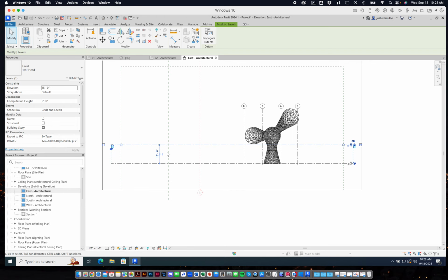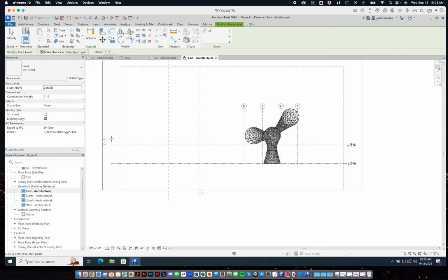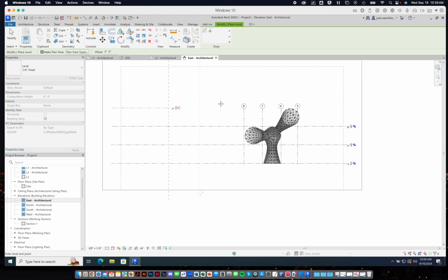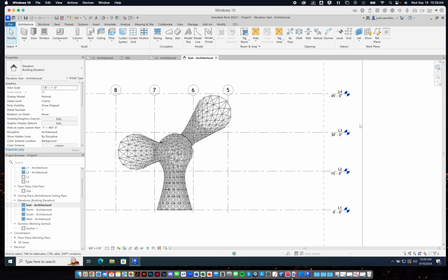All right. And let's see, I want to make another level, so I'll go ahead and do that. And I'll go 15 feet. There we go, 14.6, 15.0. There we are. 15 feet above that one. And then another 15 feet for level 4, the roof. All right. Yeah, you can see the elevation each time. So Revit's going to start labeling these things just like if you're building construction documents, right? 0, 15, 30, 45, right? That down to the ground and everything above it, its elevation. Okay.